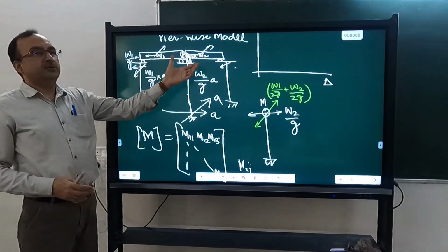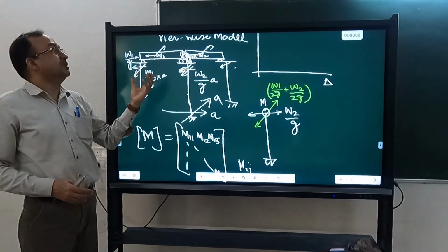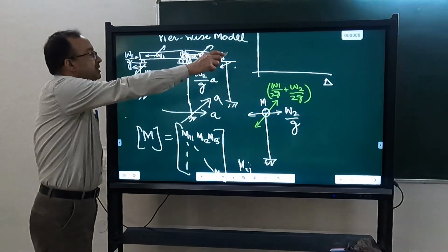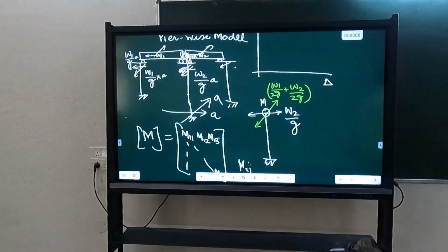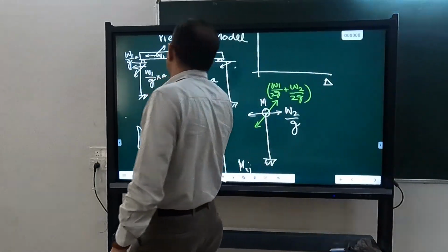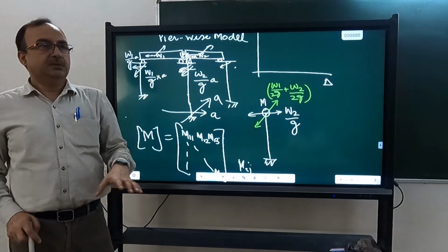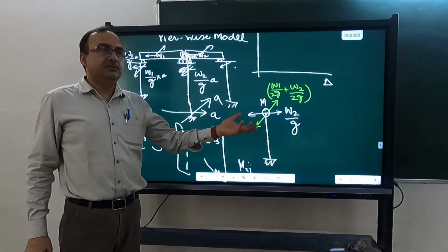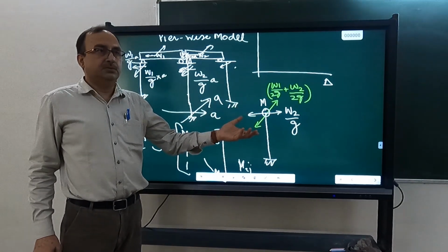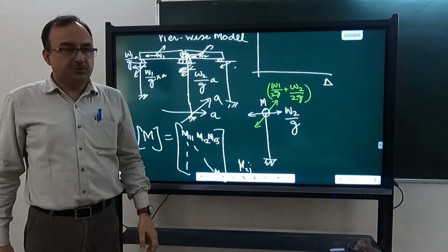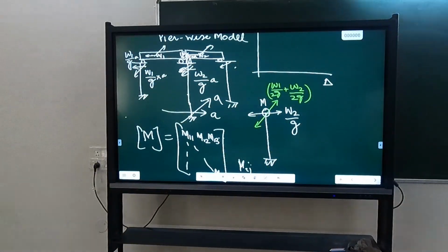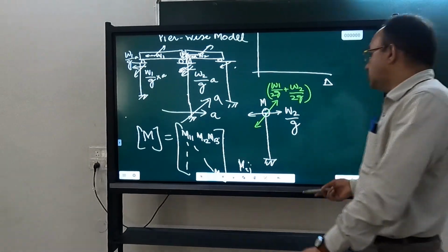We usually ignore that torsional motion. If I want to consider it, then I have to make a full model and perform a dynamic analysis. But we do a simplified model where we separate these piers and develop a capacity curve for each pier separately. There it will just act like a cantilever column. So if the bridge superstructure is simply supported, then the capacity curve is very simple. It is like a cantilever. Sometimes the piers are also framed.